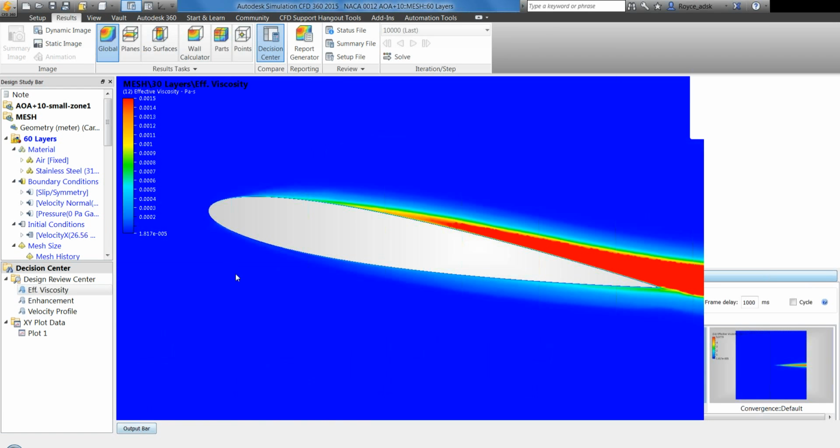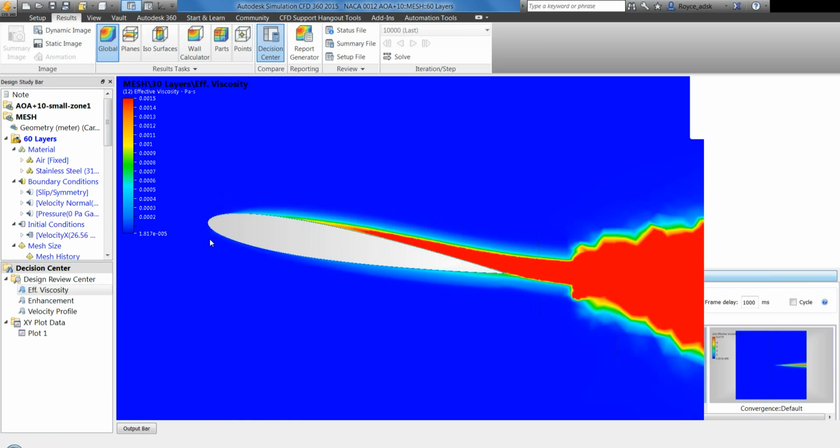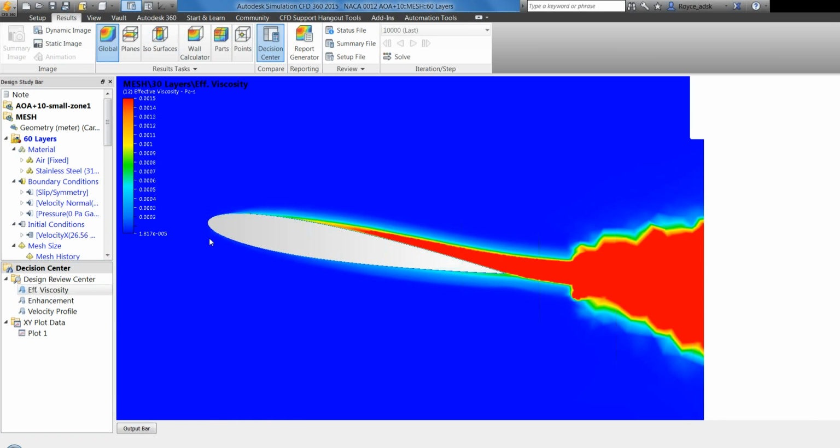Okay. Some other things you can think about within this is, when you start looking at the shapes inside of your heat exchanger, what is really going on? We have some sort of liquid going over the shapes, and depending on the channels around these shapes, I don't know what it looks like. Maybe what you really need is more mesh within the root, so that you make sure that you really allow the flow to travel through the different shapes to get a good mesh or a good result.